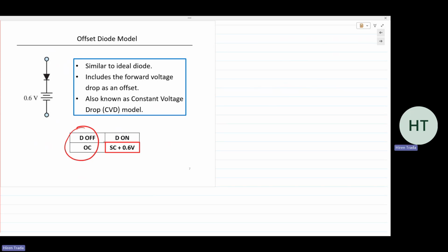So again, this is not accounting for the nonlinearity or the linear resistance there. All we are saying is the voltage across the diode is going to be held constant. So we can model it as a short circuit in series with a voltage source, because that voltage is going to be held constant. So it's supplying that voltage between those 2 points. And so the same diode that we had is replaced with a short circuit.